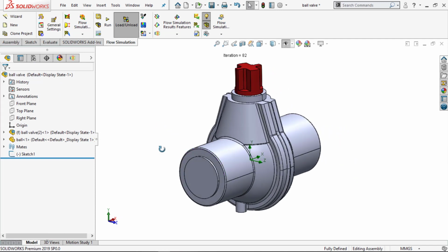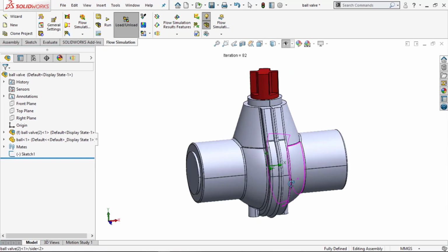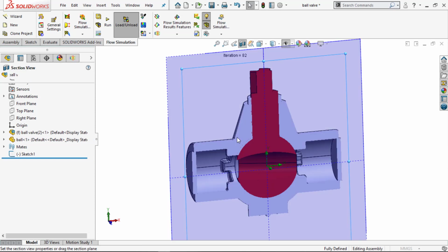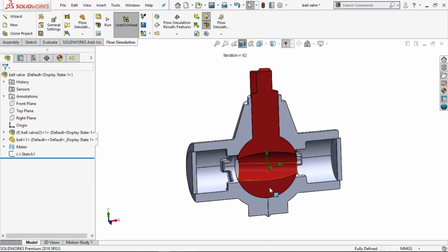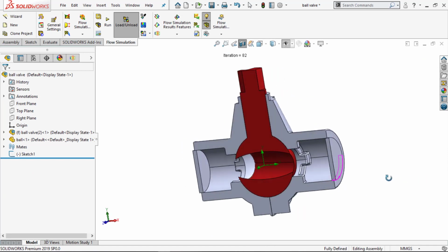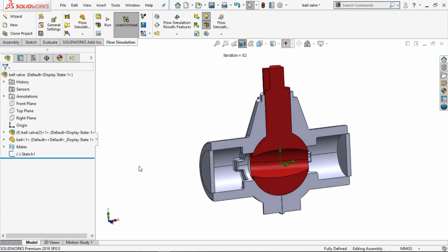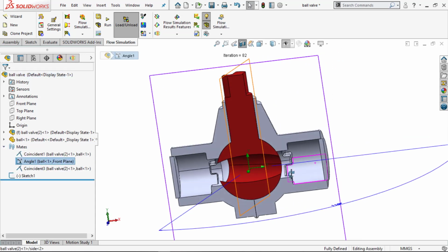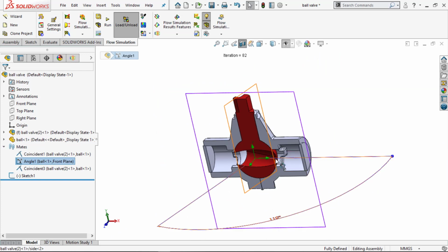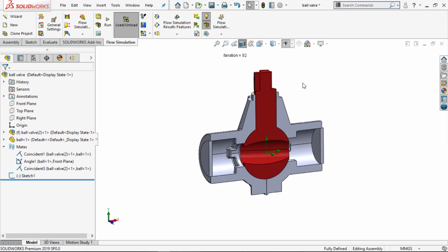Yep, this is the valve assembly. Okay, so you could already define the lids and all. You can activate the section view just to cross verify the same. I have defined the angle of attack up to a certain level so that we are able to create the pressure drop region at this wall region. Okay, if the pressure drop is more, the energy needed to maintain the same will be more. Okay, remember that. So here I have defined 110 degrees to rotate the entire knob.